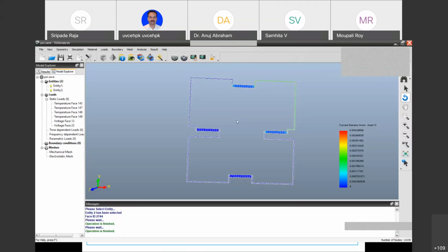That's the agenda of the tool. And other than that, you have other aspects. MEMS is one part of it. Other things are like signal conditioning systems, which are essential for MEMS devices, that can be designed and simulated as well, which I'll show you in the next module. Another is the fabrication methods. While the multi-physics device functionality is simulated on the FEM principle, finite element method or boundary element method, the nano fabrication or micro fabrication, which is a CMOS process, can also be simulated here.